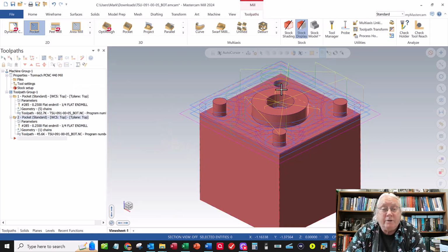Now I'm going to do, for the hole, I'm going to use a 1/4 inch drill, and then I'm going to come back and clean it up with an 1/8 inch end mill. So you're going to use a 1/4 inch end mill also. Your holes are going to be slightly bigger than 1/4 to accommodate the gap. But I'm going to show you what I would do here. So actually I probably want to use a slightly smaller drill than a 1/4 inch, so that when I clean it up with that flat end mill, it'll take off that last bit of material. But I'll go ahead and use a 1/4 inch drill, excuse me.